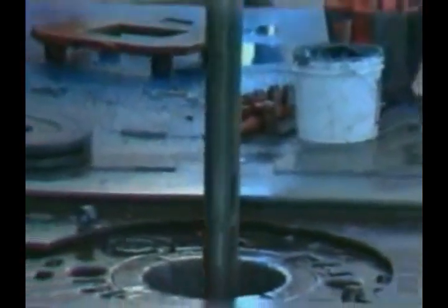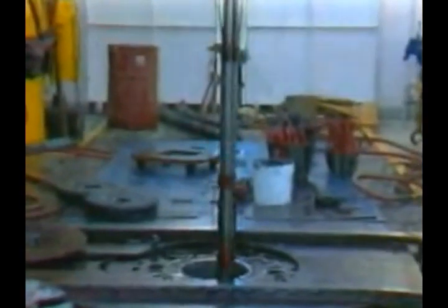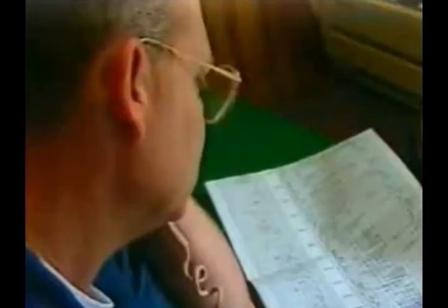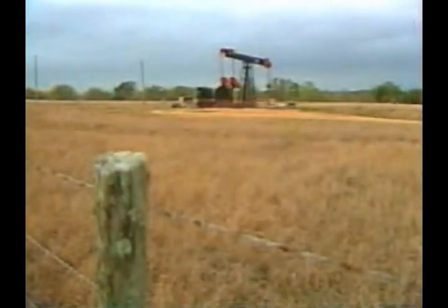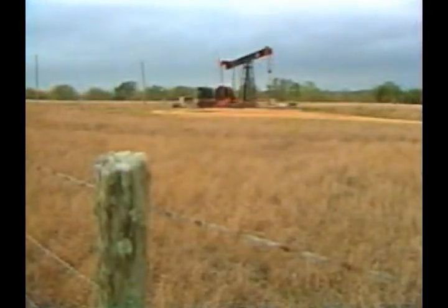Geophysicists use downhole acoustic logging techniques to determine velocity profiles in an area in order to calibrate and accurately interpret seismic surveys. And engineers use a variety of logging techniques to design completion programs and estimate the composition and recoverability of reservoir fluids. During the remainder of this module, we will emphasize open hole logging. For discussions of wireline devices used primarily in cased hole and production logging, you should rely on your manual.